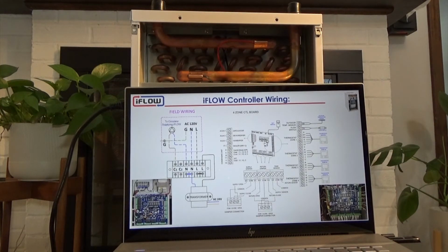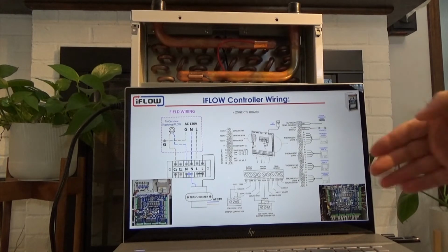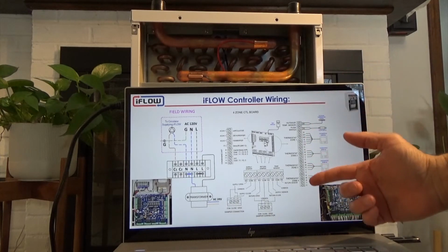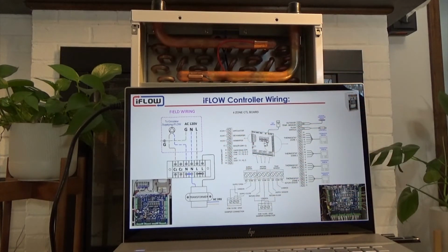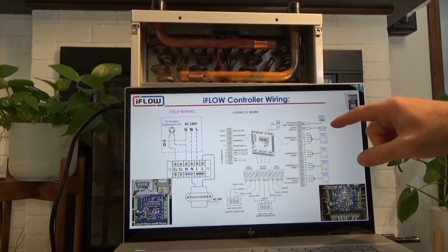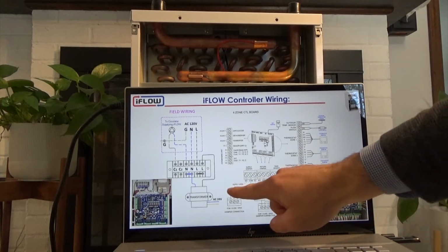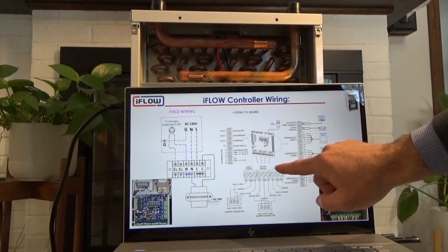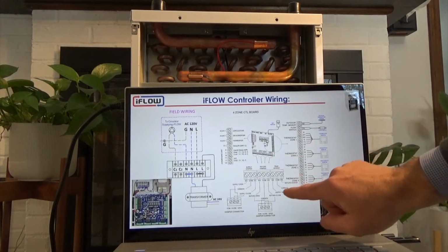So looking a little bit further at the wiring, again, as I mentioned, all your thermostats will come in on, let's say, the right side. If we're looking at this board as an example, all your dampers will come in the bottom, right? Zone 1, zone 2, zone 3, zone 4. And then they've got this kind of legend.